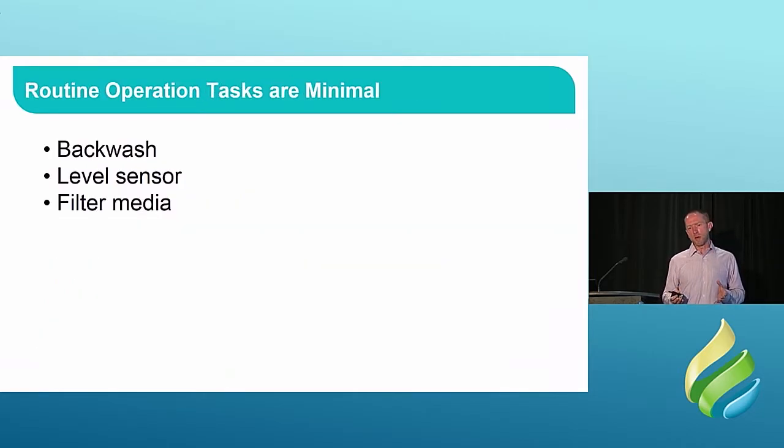So what are the things you're going to have to do to look after this equipment? It's a good idea to go in and check on it from time to time. We would say at least every week. If you're doing a daily walk around as part of your schedule, then pop in to have a look at the filters. It's certainly not a bad idea. Hang around there long enough to hear the thing go into backwash. They normally do that a few times an hour. So is the pump making strange noises, for example? It's that kind of stuff, right? Just keep an eye on it. It's kind of obvious, I suppose.